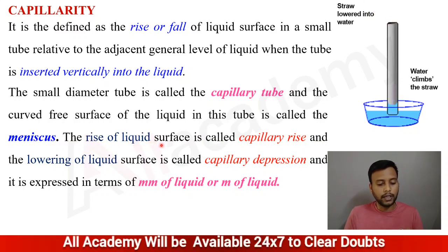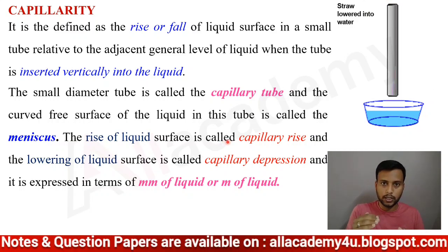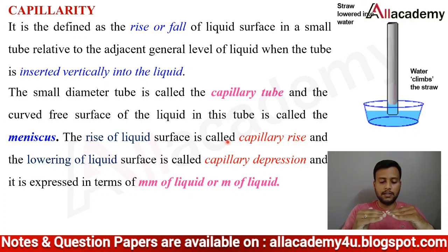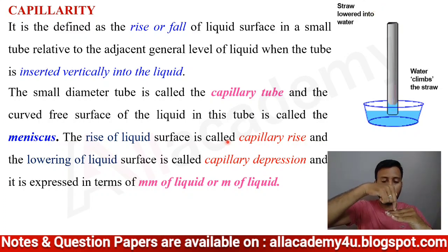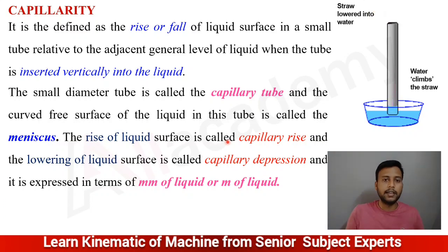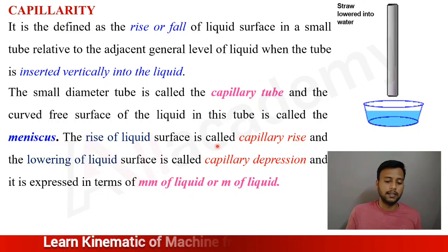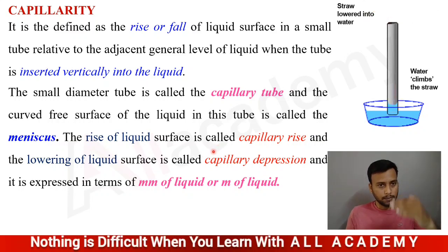Now the rise of the liquid surface is called capillary rise. When I insert the tube, if the water level in the tube comes above the adjacent layer, then it is a capillary rise. Similarly, if the water level comes below the adjacent layer of water, then it is a capillary depression.